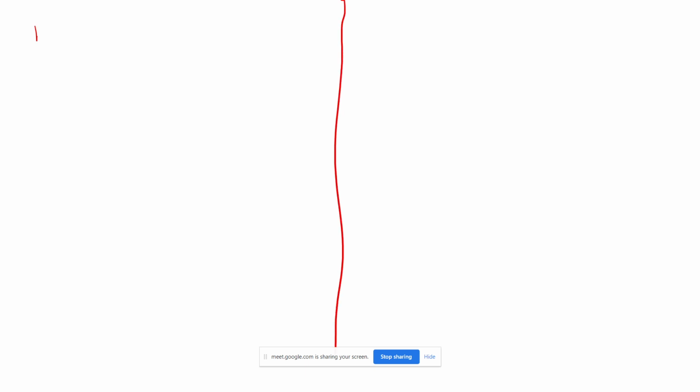So what will be H2? 137.88 plus 0.6488 into 2561.42 minus 137.88. From here, what will we get for H2? Directly I am writing the answer, 170.3 kilojoule per kg.